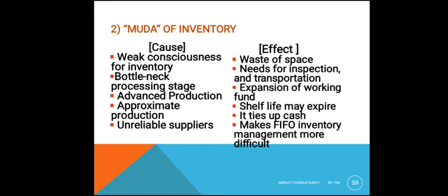The cause is weak consciousness of inventory, because some workers and some organizations may create inventory because they do not know the harm of it. Other causes are bottleneck processing stages, advanced production, approximate production, and unreliable suppliers. The effects it brings: waste of space, needs for inspection and transportation, expansion of working funds, shelf time may expire, tied-up cash, and it makes FIFO inventory management more difficult. This is the first in, first out philosophy,